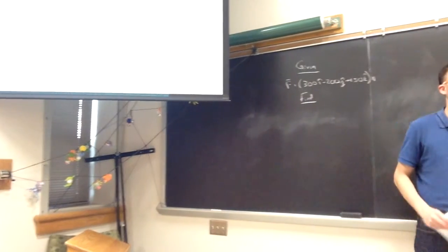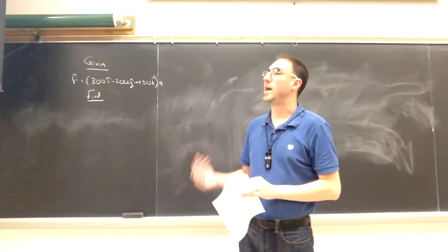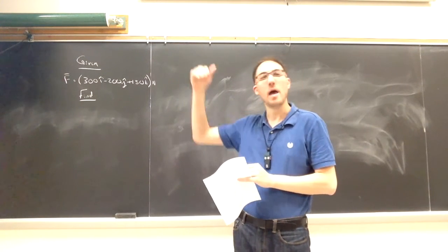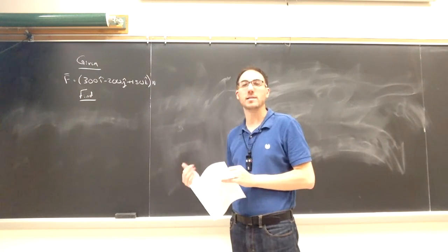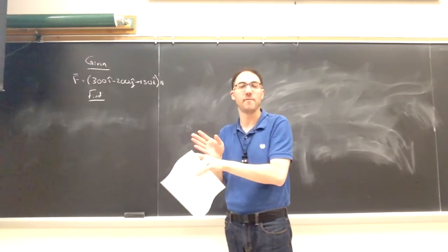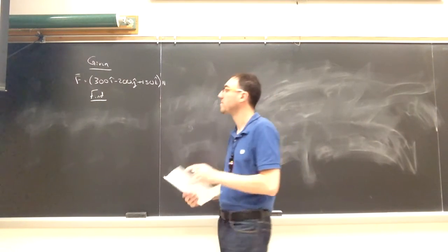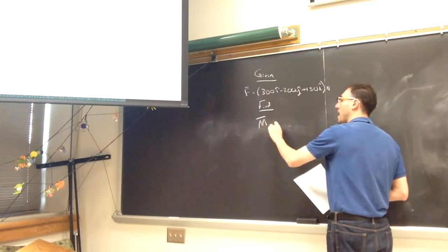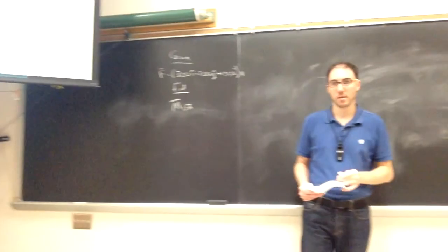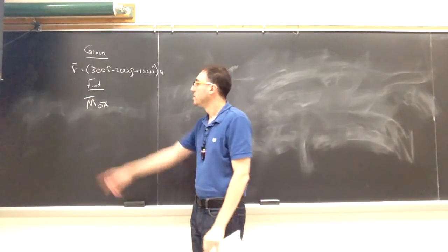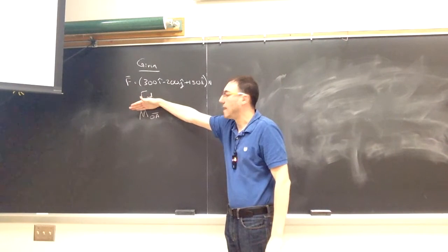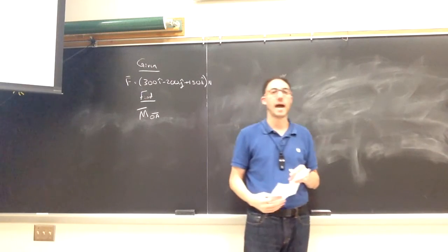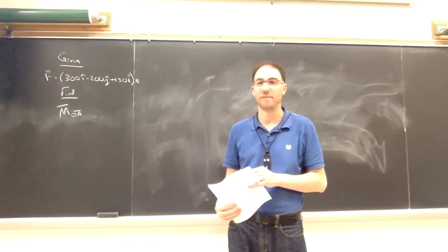And again, what we want to find is the moment about the axis AO, or in this case, OA. There is actually a difference. It starts at O and points towards A. So the OA axis and the AO axis lie on top of each other, but the direction will make a difference. So we want to find the moment as a vector around the OA axis. It's not just the magnitude, which would not have a bar over it, but I want the vector form of the moment around the OA axis due to, in this case, a single force F.